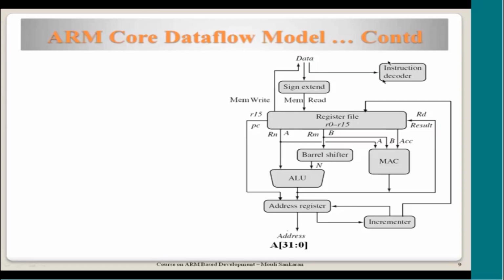Now the instruction gets decoded, and based on the opcode and the operand registers mentioned in the instruction, the decode logic generates some control signals to transfer information from one register to another. So that is what the decoding logic does, and then during the execution, some of the registers get opened up and the data flows into the proper registers, and the instruction gets executed.